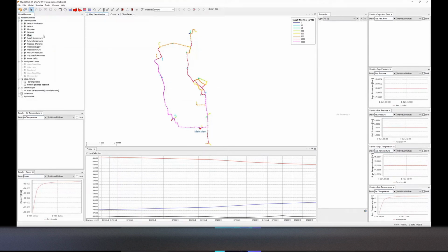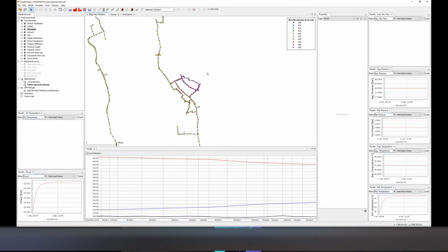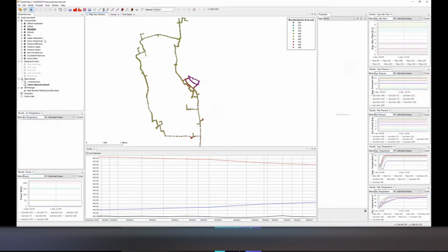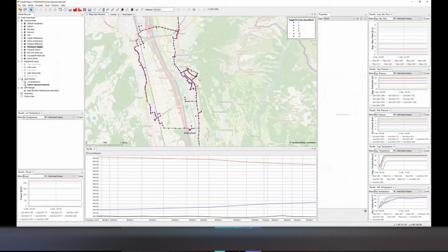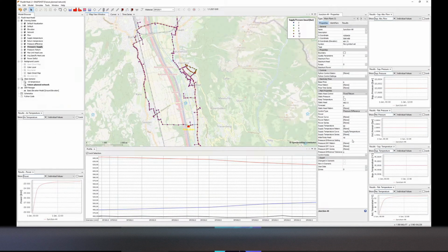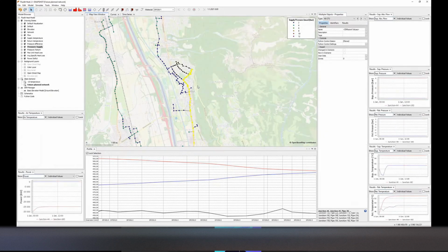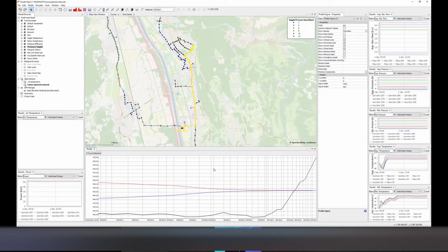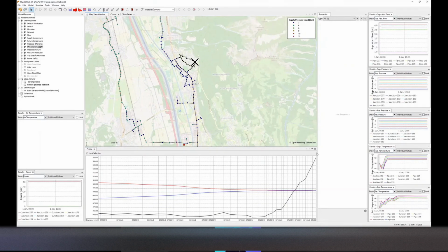What might still be some problems that my network is now experiencing? This area here is extremely high, and if we look at supply pressures, let's keep, for example, 2 bars at the main plant, and what would be the profile when going to this high location? It is just going on a bit of a mountain there, so obviously our pressures are not sufficient to supply here.